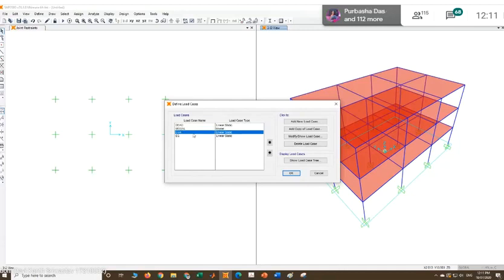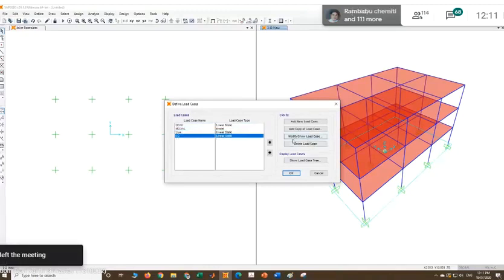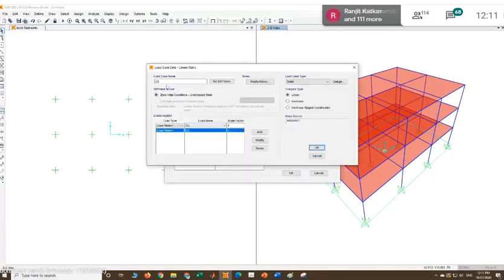Okay, so I'm going to live load, dead load. I've shown you live load will also be linear elastic, and earthquake load also linear elastic. Since I'm showing first of all equivalent static analysis, I'll change the name here to equivalent. Okay, let's keep EQ only to prevent any confusion.